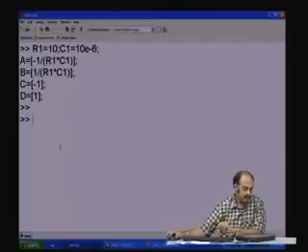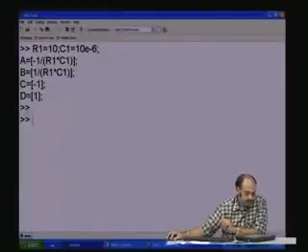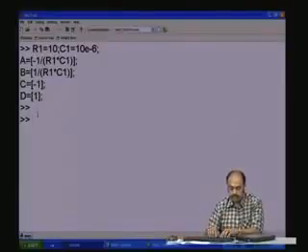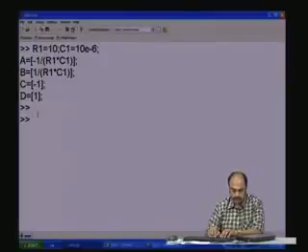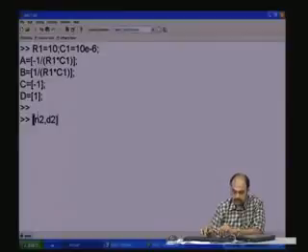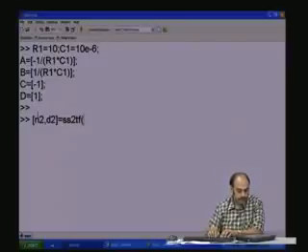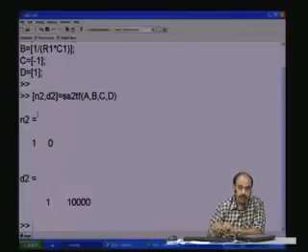We can now get the transfer function of Vr by Vi. Now, we perform the same operation, that is, we get the numerator polynomial and denominator polynomial of the second transfer function by state space to TF conversion of the A, B, C, D matrix. Now, this is going to give you the numerator and the denominator polynomial.